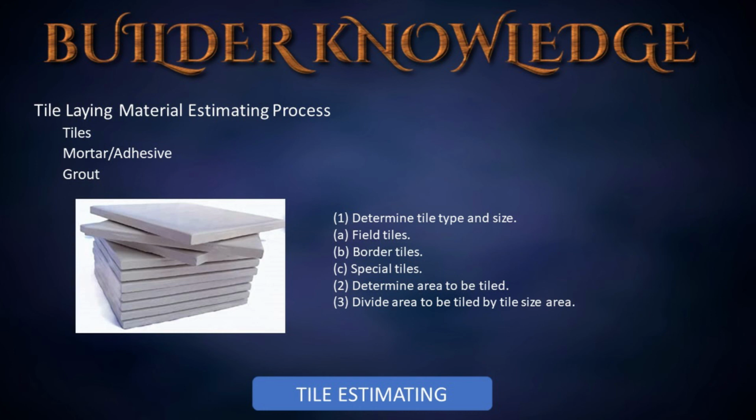Hello again, and thank you for asking. To figure out how many tiles are needed for a specific area, multiply the tile length by the width to figure the area that one tile will cover in square inches. Divide the result by 144 to convert it to square feet. Then, divide the area you're tiling by the square footage of one tile to determine how many tiles you need. Thank you, Petty Officer Google, I've got it now.